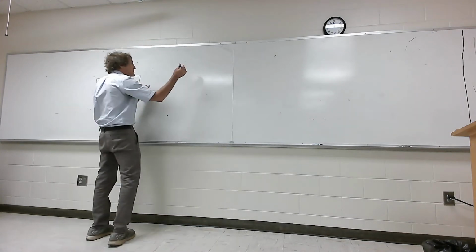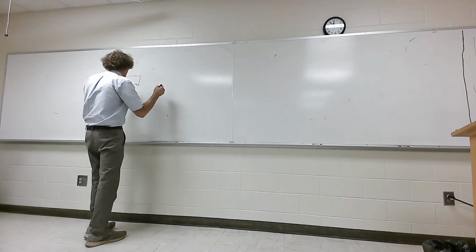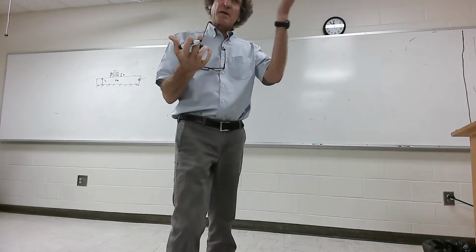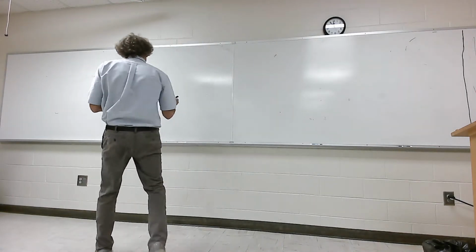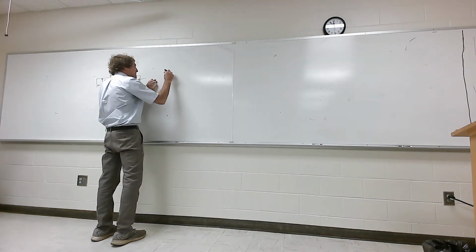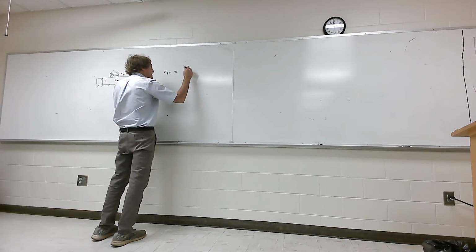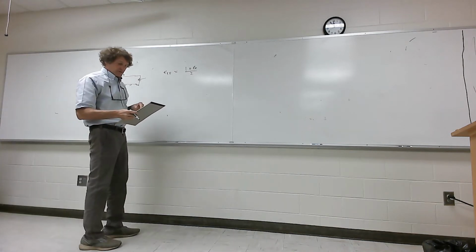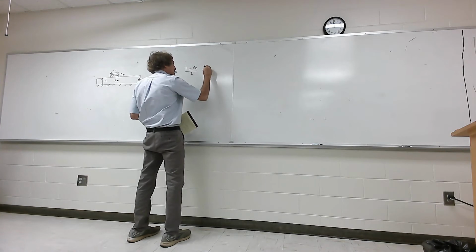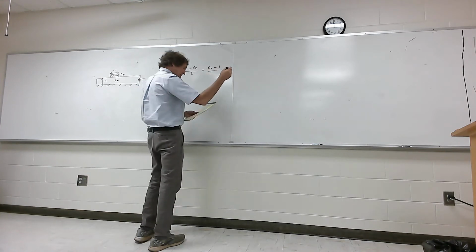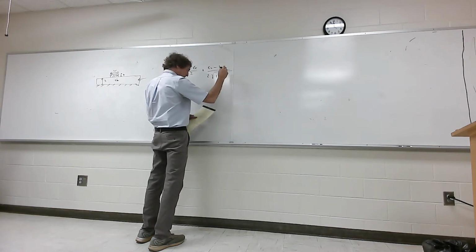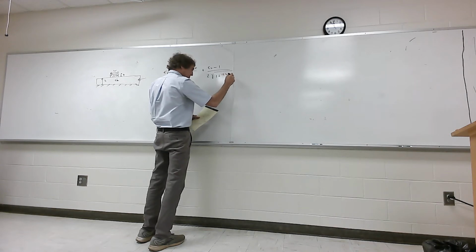So when you have this, there's something that they talk about. The first thing is the effective dielectric constant. You have dielectric on one side, but not on the other. So they talk about the effective dielectric constant, and it's 1 plus epsilon relative over 2. Actually, there are probably several different ways to write this same equation. It's plus epsilon relative minus 1 over 2 times the square root of 1 plus 12 H over W.